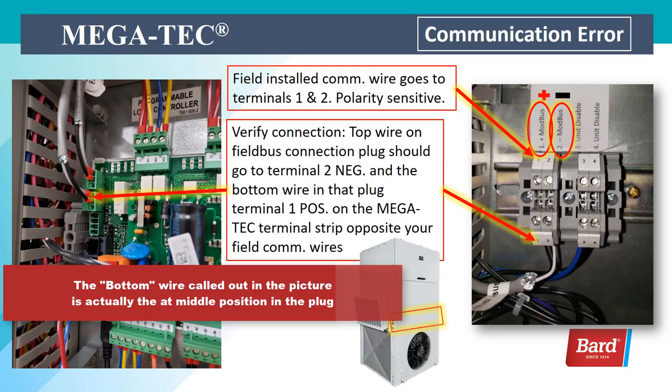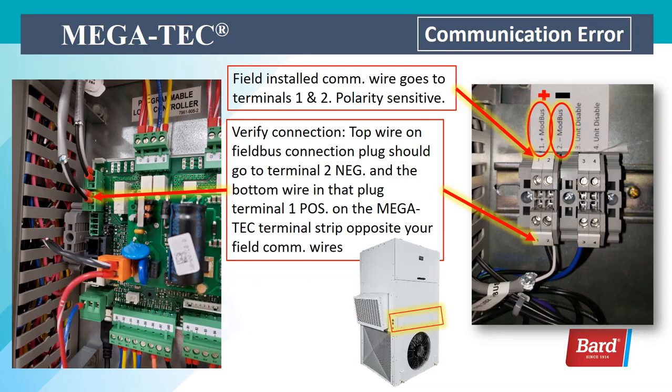This is where our PLC connects to the terminal, and on the top of that terminal where it says positive Modbus and negative Modbus, that's where our field wiring connects to that terminal strip.